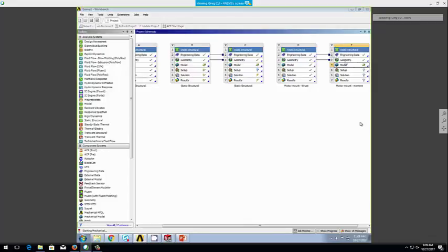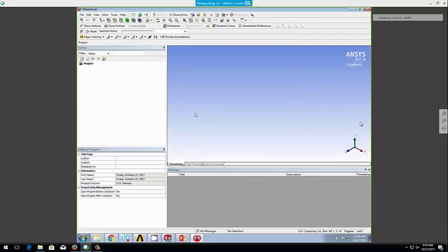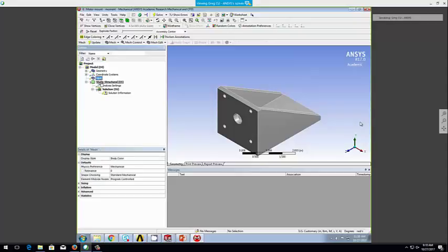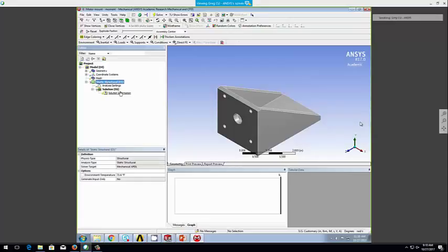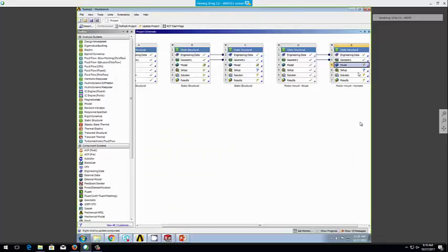So start with just maneuvers, takeoff, landing, maximum turns, maximum pull-ups, and then we'll add flying through gusts, which is important for commercial aircraft, may provide some of the highest loads, getting in a storm or getting into clear turbulence. For us, we'll bounce around a bit, and probably the turns and pull-ups, particularly during your launch period, may set your upper limits.